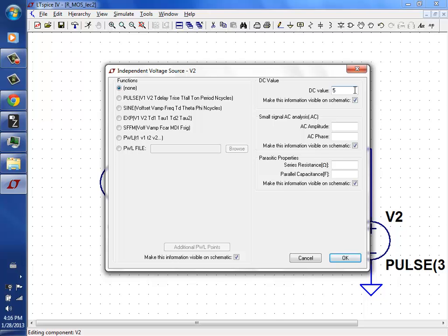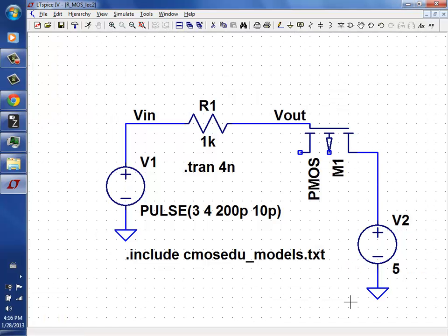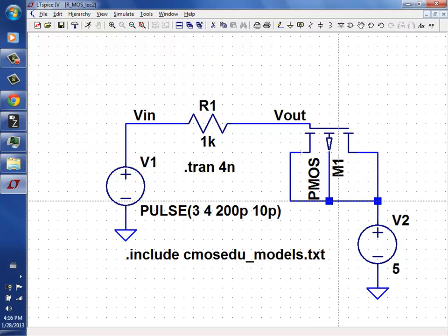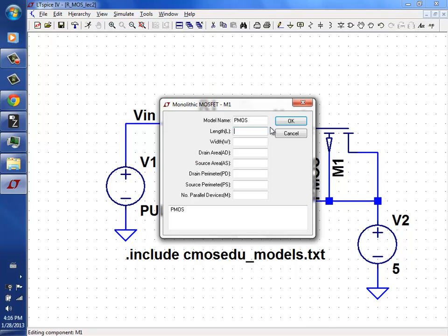The learning curve isn't like this when you have to actually do something. Okay, so then it's a DC, and I can come down here. And then right click on that, 100U, 100U, set the SPICE model, PMOS, what's it called? P underscore 1U.